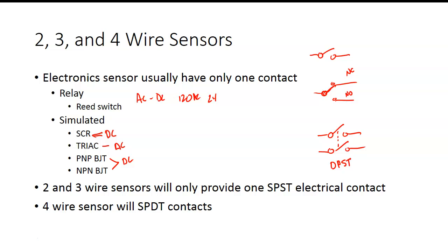So you take PLCs, the PLC that we have for PLC 1 uses relay output. We're using DC on what we do as well. If you look at one of the 1100 PLCs, they have relay outputs and they switch 120 volts AC. So that's the big advantage.